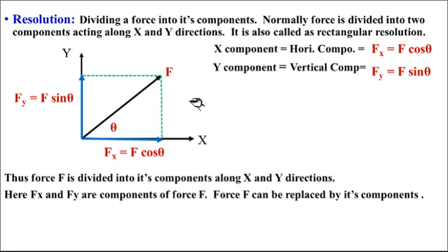Now first of all we are going to just concentrate on resolution. So given force F, as already I have explained, you have to resolve into X direction, you have to resolve into Y direction. So X component or horizontal component, X component means what? In this direction, or horizontal component Fx. Here suffix X is for X direction. So component of this F in X direction, Fx will be equal to F cos theta. This angle is theta. Okay. So in X direction, if you want to resolve, you take cos theta. In Y direction, if you want to resolve it, you take sin theta.